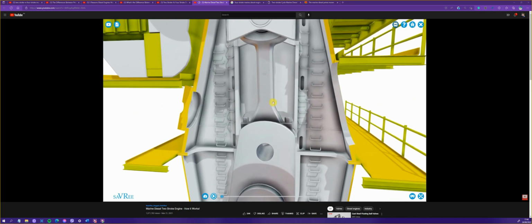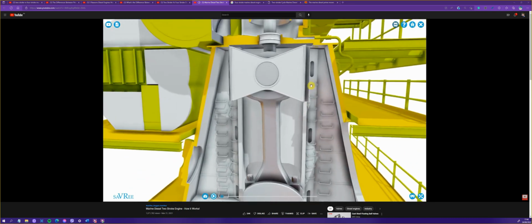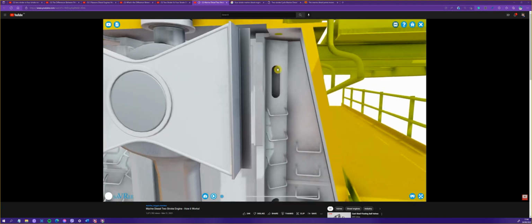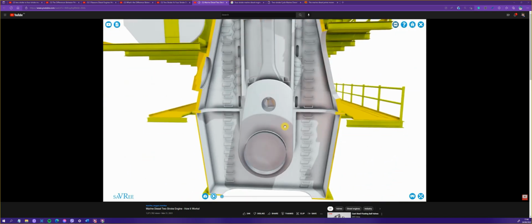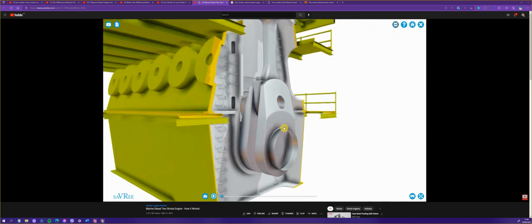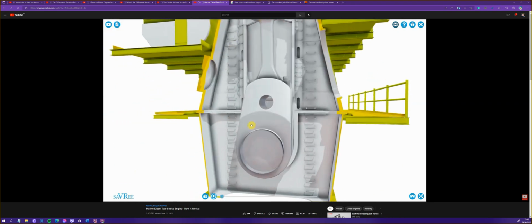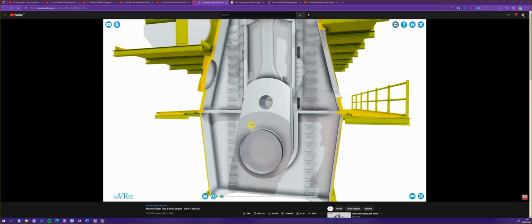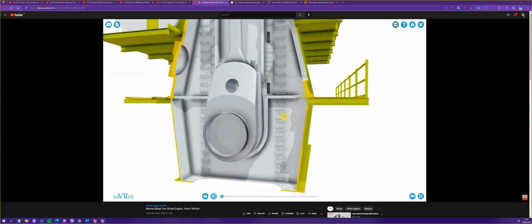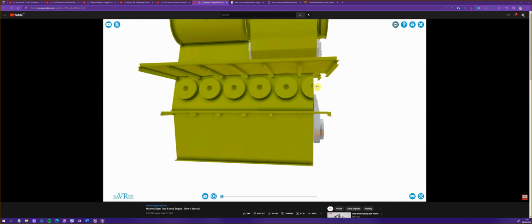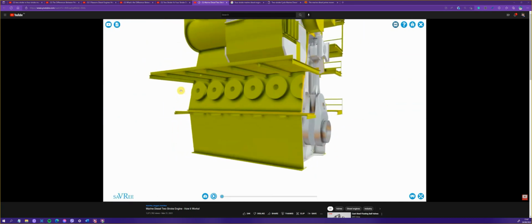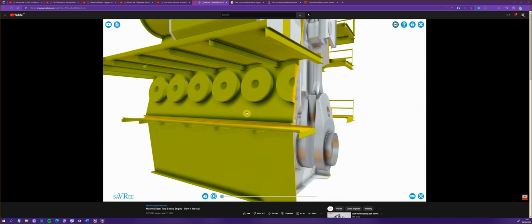This vapor then begins to accumulate, let's just imagine, in the top corner of the crankcase here. And this cloud of oil vapor will get bigger and bigger. And eventually it might actually reach back onto the hot spot that originally created it. If this happens, we might end up with combustion. If that happens, we might end up with an explosion. And if that happens, then all of these valves on the side of the engine here are designed to pop open and relieve the pressure in as safe a way as possible.